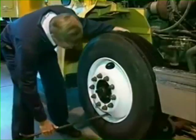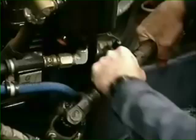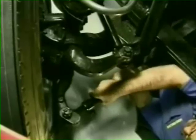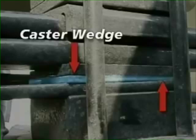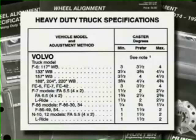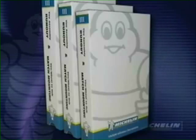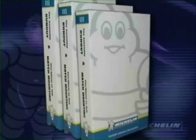Check for worn kingpins, loose wheel bearings, or loose U-bolts. Check for looseness in the steering gearbox, tie rod ends, and drag link ends. A difference in caster from side to side of larger than 1/2 degree, or caster larger than manufacturer specifications, can also lead to a front end shimmy. A separate Michelin video is available that details correct procedures for tire mounting, balancing, and correcting runout.